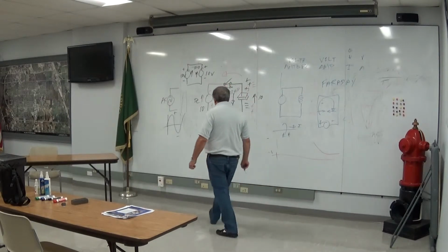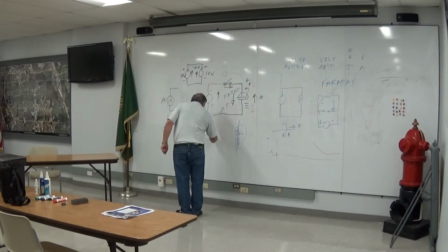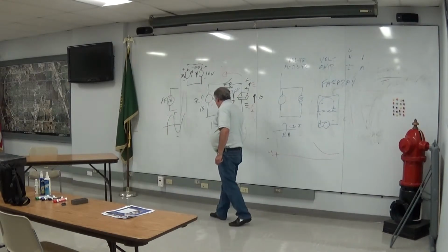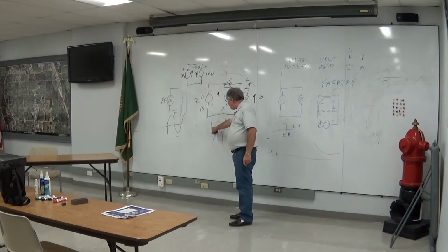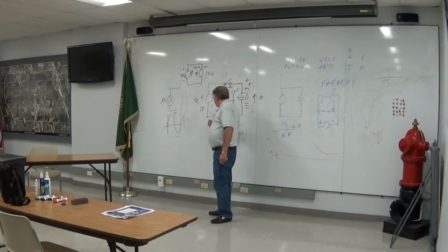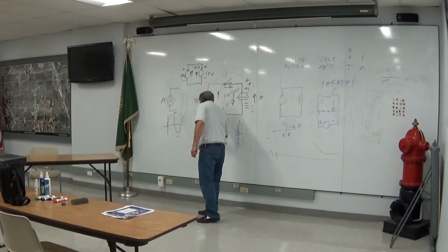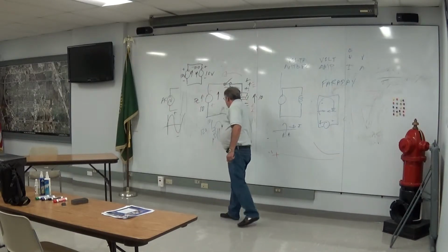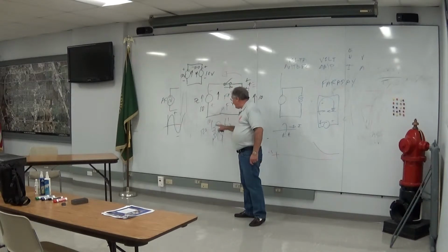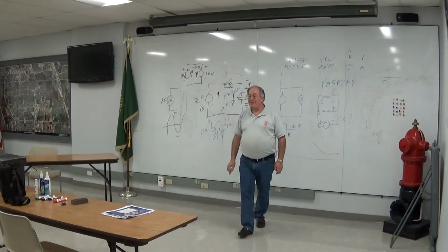When they build a transformer, the voltage in to one winding produces a coupling by the magnetic field to the secondary winding, and the turns ratio, how many turns of wire you have here versus how many turns here. If there's 10 times as many turns here as you have here, you put 120 volts here, the turns ratio will determine the voltage out. So you put 120 volts in, you get 12 out, if you have 10 times as many turns here as you have turns there.